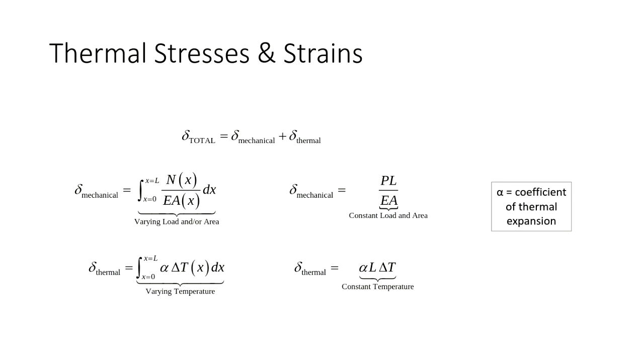And this comes directly from when I teach mechanics of materials. When you have an axial member, a member that's longer than it is wide and deep, maybe something like this I shape, I propose that the way you would express its total axial response or axial deformation is a function of either its mechanical deformation or its thermal deformation. What I mean by mechanical deformation is just PL over EA. That's what I have in the upper right expression. That's a formula, and we dealt with that last week, and it should be pretty straightforward.